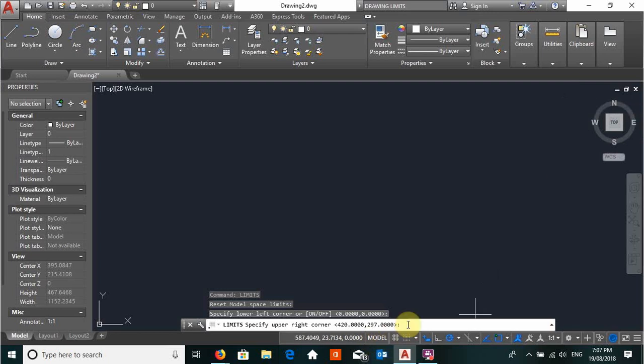All right, so we're going to type in. Of course I've got dynamic input on, so it's prompting me in blue already, or I can just write it in the command line down here just so that everyone knows what I'm talking about. We're going to do our X value first, which is 3,000. We are going to lock that in by pushing a comma, and then we're going to do that again with 3,000. Okay, and we are going to say enter.